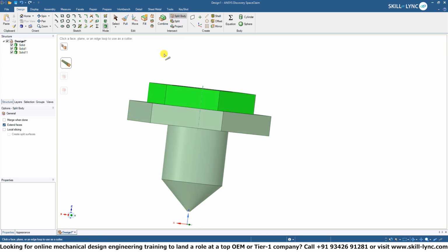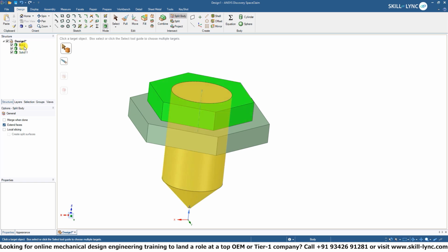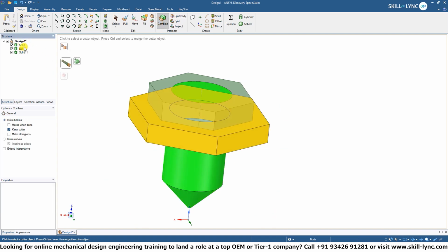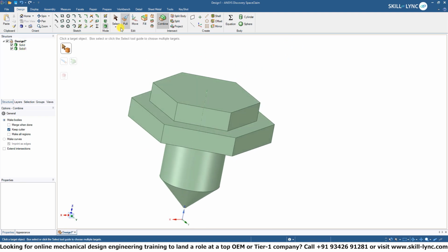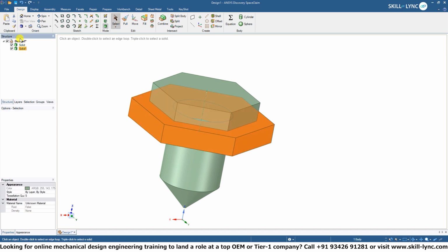So we have this top edge, which we can combine with, actually, if I go back onto the combine section, we have this middle surface that we can combine with this surface. And pretty much what we end up with is the same effect, but with less geometry drawing.